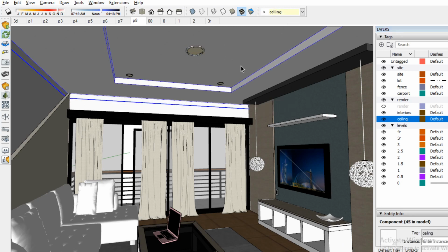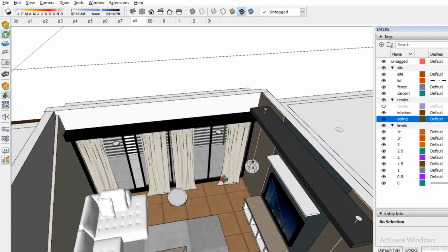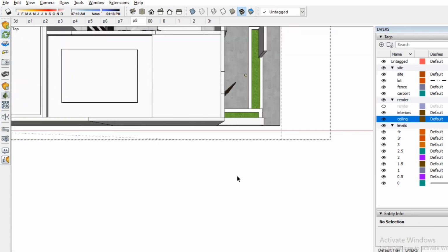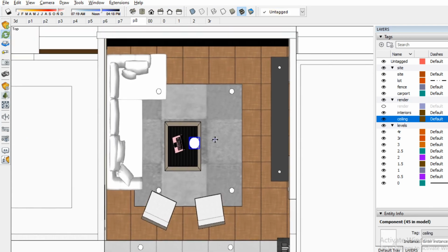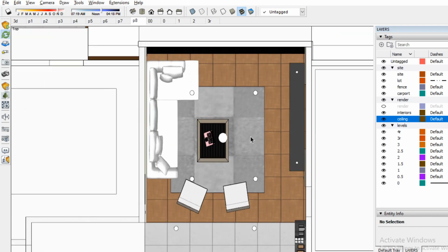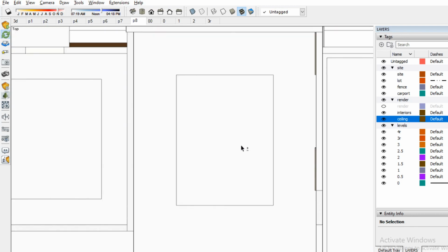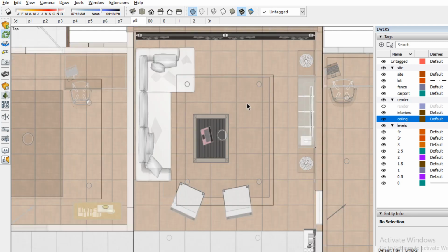This is so that I could just press H to hide the ceiling and go to top view to arrange my lighting fixture layout. This makes it easier instead of looking from below like the reflected ceiling plan, having a hard time to model. Once that's done, I just unhide the ceiling and you could see the arranged fixture that I wanted to lay out.